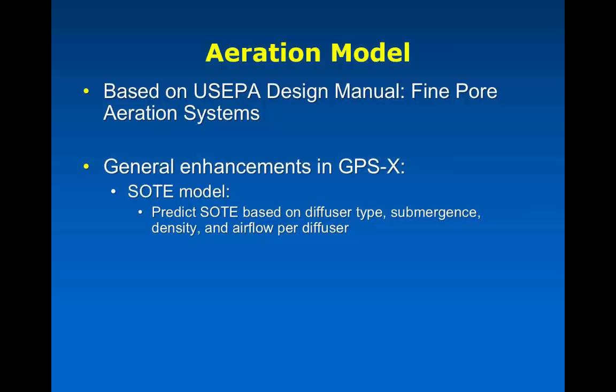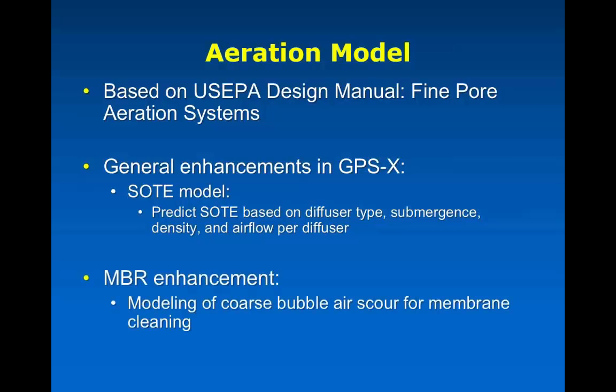Those things are now actually calibrated differently by default in the MBR unit than you would find in the regular tanks. One thing I will mention as well is that just recently we updated the tuning for the DO controller in the MBRs, so it is now also different than what you would find in the conventional activated sludge tanks.